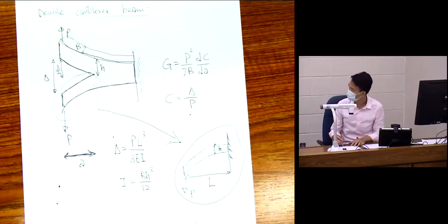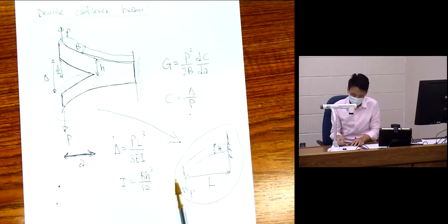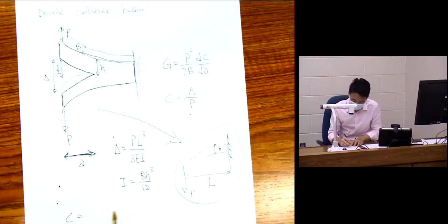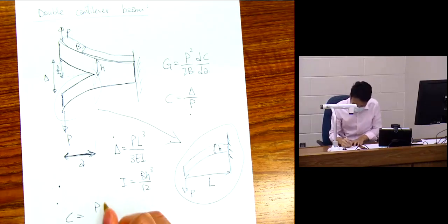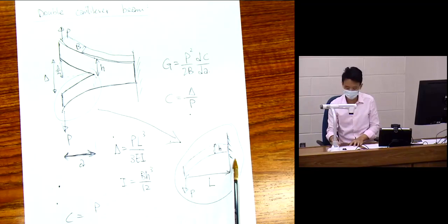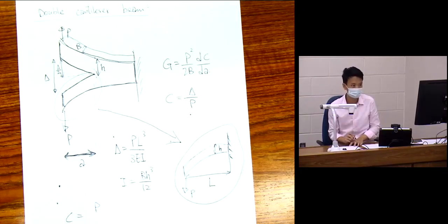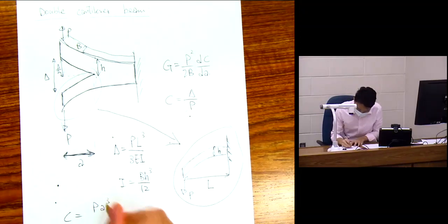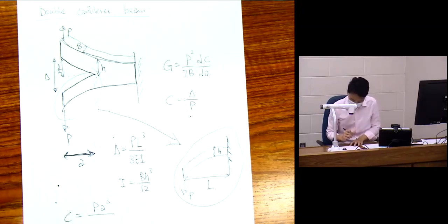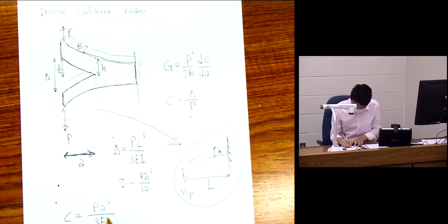So just collecting all this, I know the delta is this guy. I just calculate what C is. C is delta over P. Now L is the length of the beam, and that is the crack length, exactly the crack length A. So it's just A cubed here, over 3EI, that's delta. Oh, sorry.